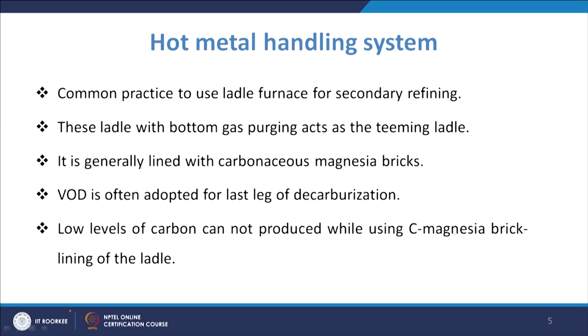The gas purging is done from the bottom, and that acts as the teeming ladle. It is generally lined with carbonaceous magnesia bricks. That is the normal practice.